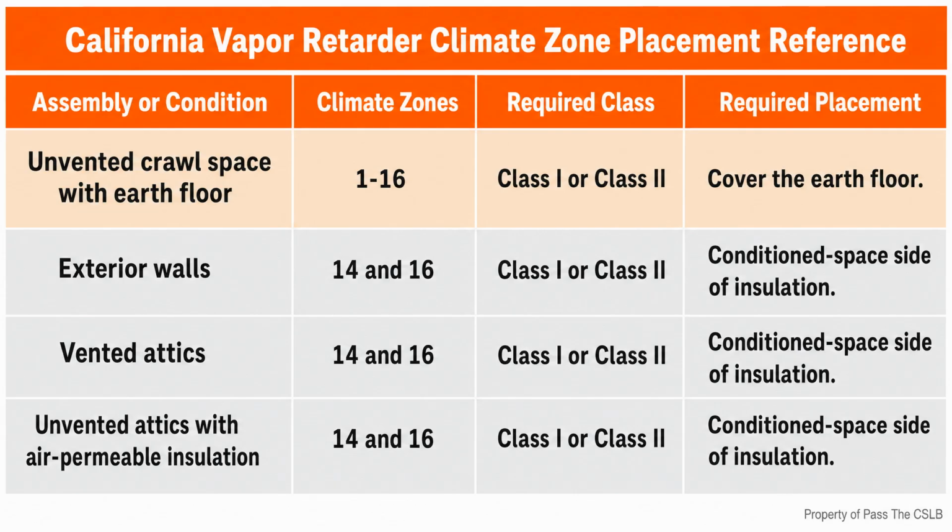Openings still require coordination with the approved flashing details. A field crew should not treat the felt lap numbers as a complete window or door flashing design. The water-resistive barrier, flashing, and opening installation have to integrate so each upper drainage layer releases water onto the layer below. When a detail is unclear, I want it resolved while the opening and surrounding layers are still exposed.